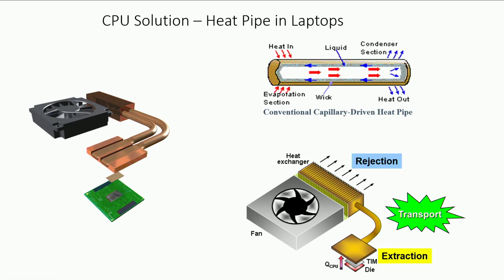Now, how will the liquid be brought back? That is the question, right? How do you pump it back now? The way it is pumped back is by a material or a layer called a wick. So, if I take this circular pipe over here, as you can see, the annulus has a material which we call the wick. The wick can be a fiber, it can be sintered metal, various things. What it does is, because of the capillary action, the condensed water drops flow back through the